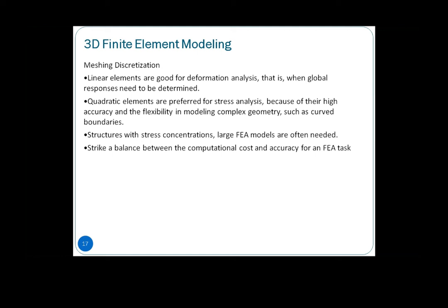Then probably it will help you. Even without the experimental validations of your model itself, the mesh independence test at least will tell you something. It means that it is approximated with a correct mesh size, with the correct assumptions on the boundary, the supports, and even the contact itself, to represent the actual physical behavior of our actual system.